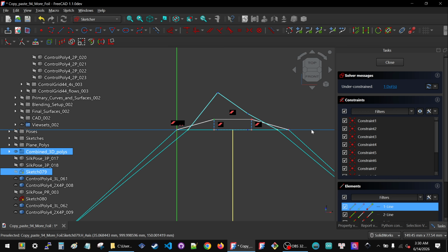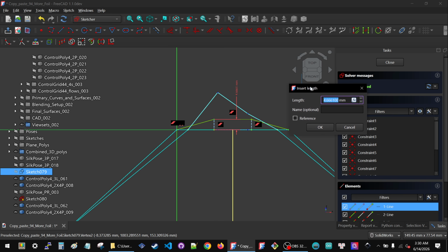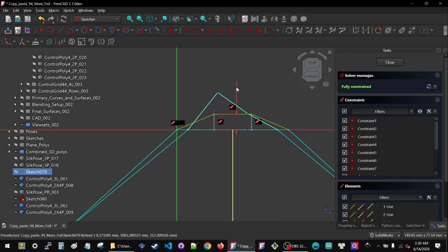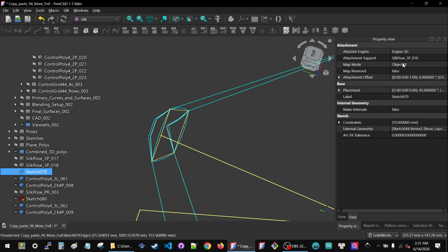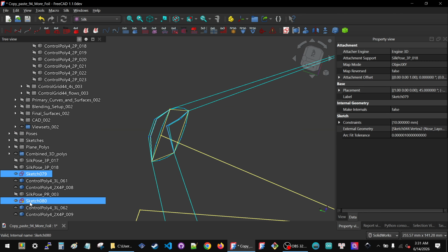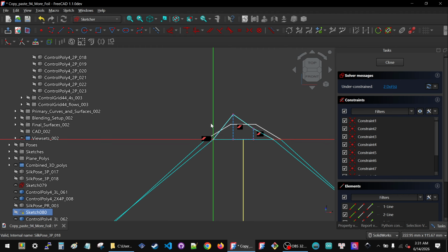So I'm going to set the height. That's the only dimension in this sketch, from the axis to one of these points. And I'm going to go as high as I dare, but not aligned with this line and not above it. I'm going to try 7. That's still okay. I'm going to try 10. That's still okay. And that's as far as I'm going to go. I'm not going to get any closer to being aligned. You can see a distinct angle between these two lines. It's safe. Close. Do a similar business on this curve here.